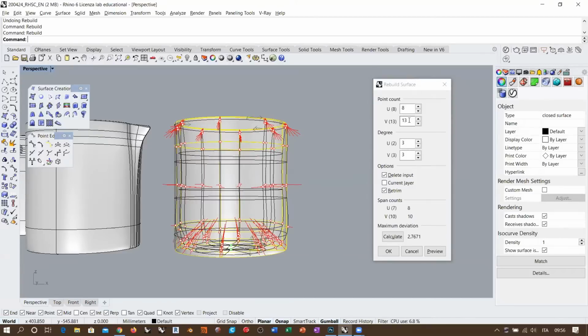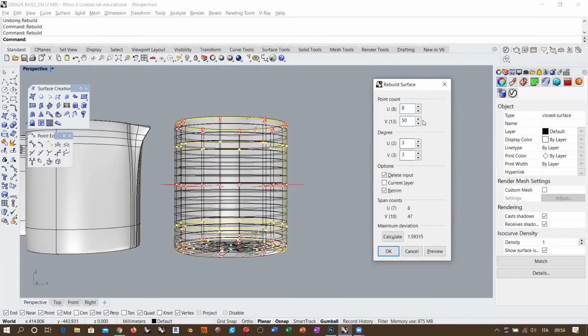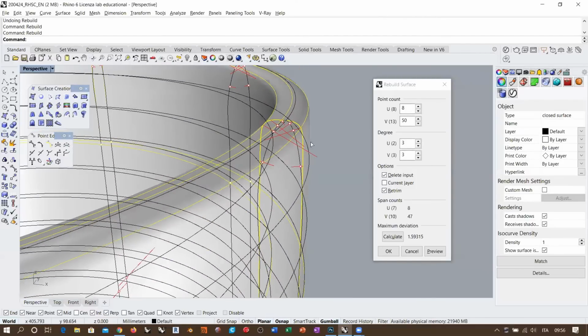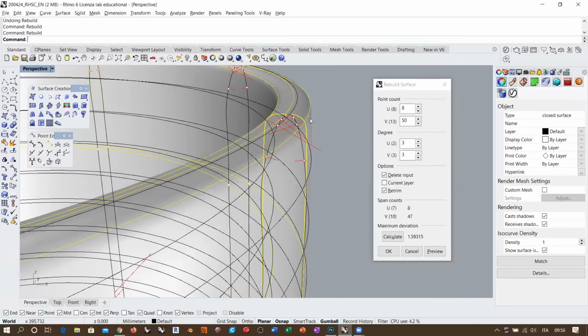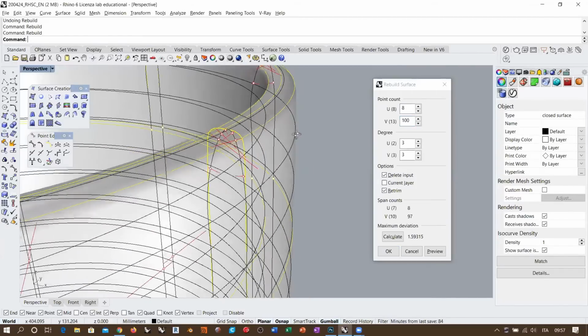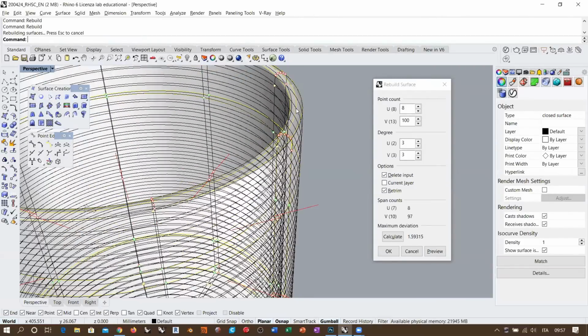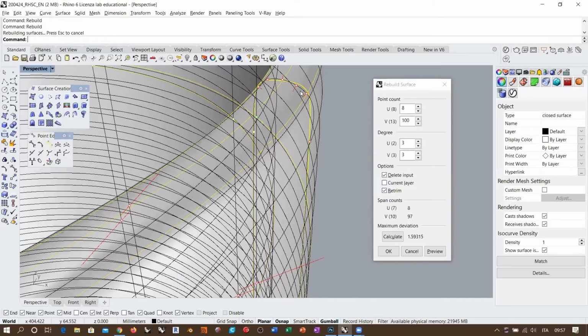Okay, so these are very few control points because they are evenly distributed along the path. So I need way more than that. Okay, so if I do this, for example, you see that I start to go back to a more controlled situation, but this is still not enough for the upper part of the glass. And so here, for example, if I increase to 100, I should start to have a more precise representation of the upper part, yes, but I still have this kind